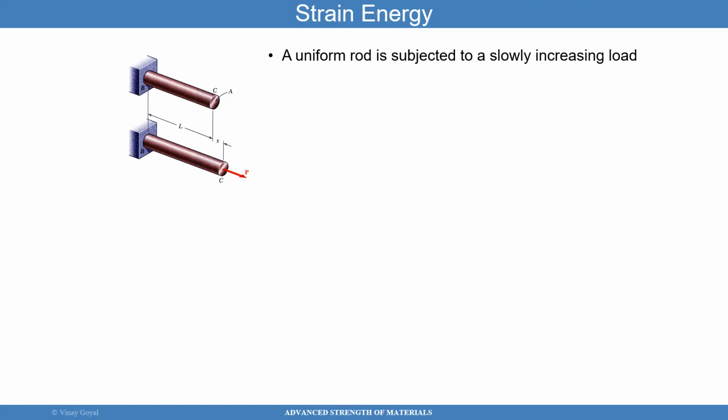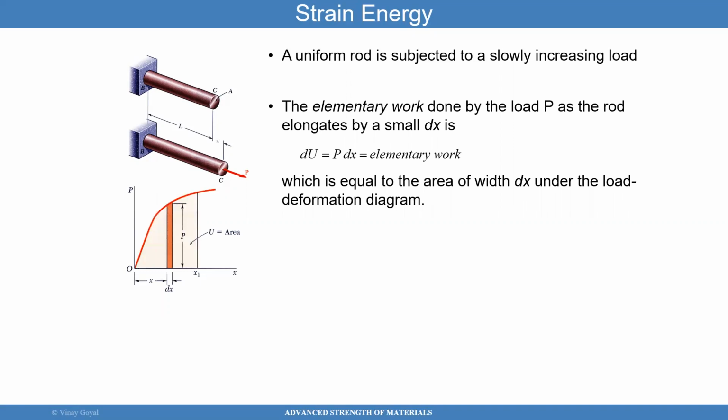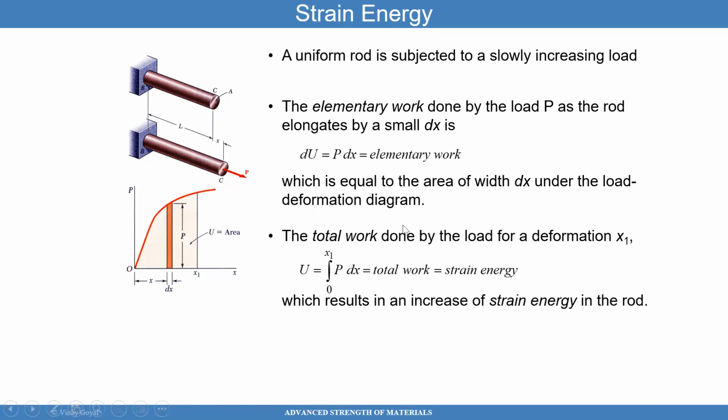Anytime you apply a load to a structure, that structure is going to contain some amount of strain energy stored. And when you apply a load to a structure, there'll be work done due to that load applied. In this case, I want to cover a few examples about that. If I plot the load versus deflection here, the energy under this curve is the energy due to the work done by the load applied.